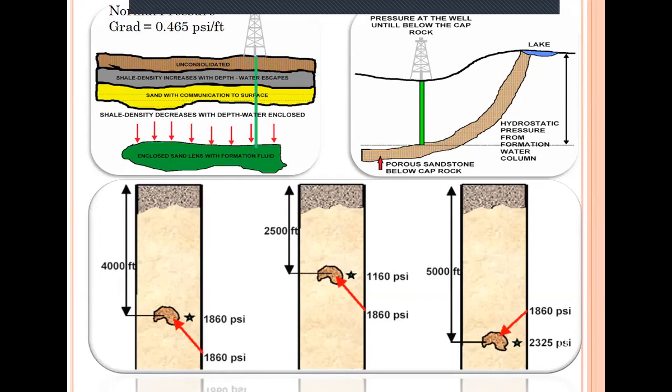Why? This is the main point of why we are talking about pore pressure in this presentation. This is the abnormal pressure. You found a formation which, in most cases, is a sand lens entrapped with shale formation. You will find its pressure higher than expected. And maybe you have a shallow gas kick, or maybe you have a kick and you close your well and increase the mud weight and so on.